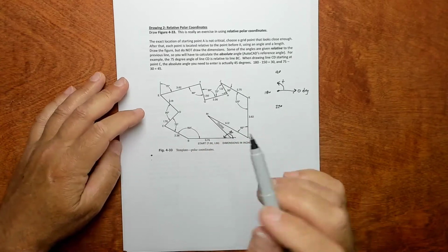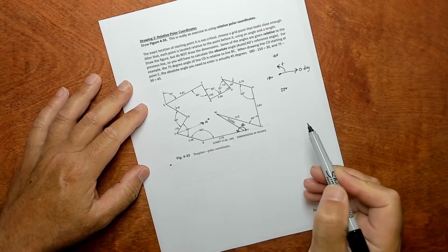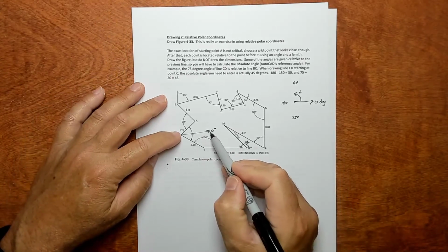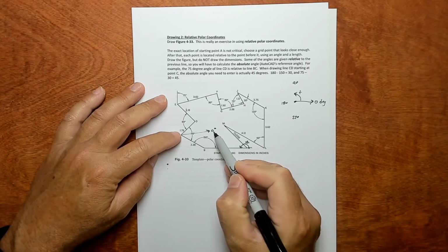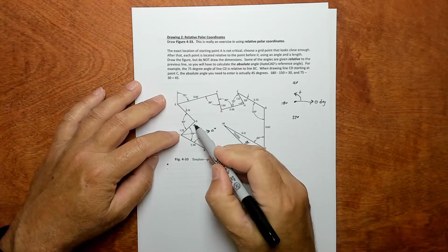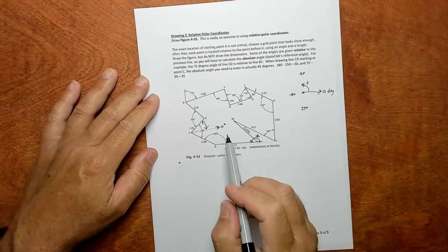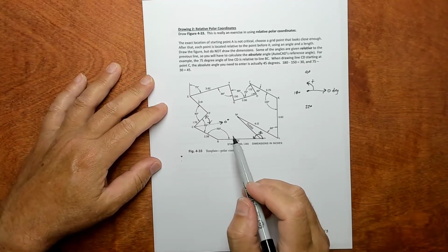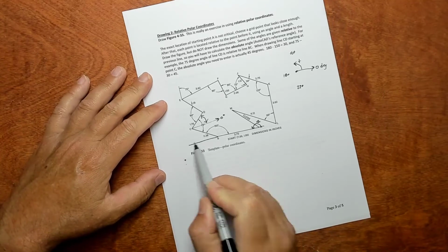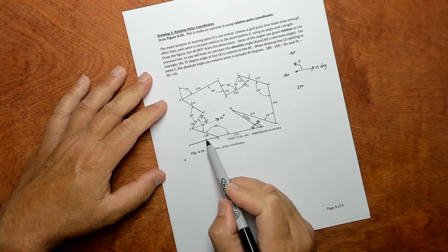Now this CD is a little bit trickier, because this would be 0 degrees, right? Just straight over would be 0 degrees. But for AutoCAD, we need to enter the angle in absolute, really. So we need this angle right here. And what is that? Well, you got to sort of figure it out. It's a good review of trig and just get you thinking the way you need to think for this material. So let's figure if we had a straight line over here, what would this little angle in here be?